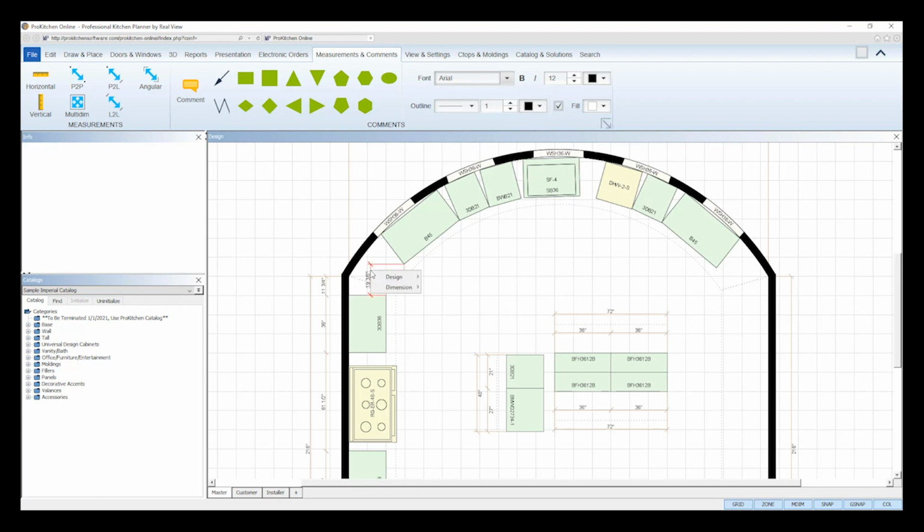Again, you can right-click on the dimension and use its toolbox to move its position. You can also adjust only the left or right extension of the measurement line by clicking on the left or right EXT tools in its toolbox. This time, just the extension will move in the direction of your mouse, and you can click again to lock it into position.